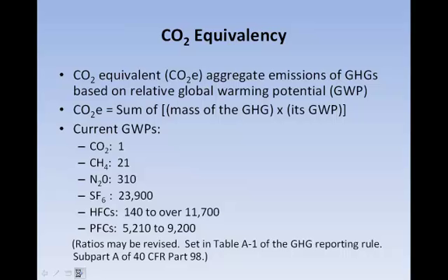Under the Tailoring Rule, applicability is determined in a 2-step process that evaluates first whether the CO2e emissions are subject to regulation by being over the regulated NSR pollutant thresholds, and second, whether the mass emissions are over the PSD, major source, and/or significant emissions rate thresholds that are part of the traditional PSD program.